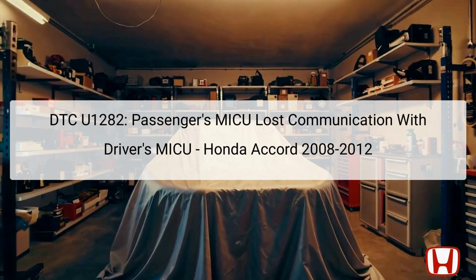The DTC U1282 indicates a communication failure between the passenger's multi-information control unit, MICU, and the driver's MICU in the Honda Accord model years 2008 to 2012. The MICU is a crucial component within the vehicle's body control module system, responsible for various functions such as lighting, security systems, and power windows.